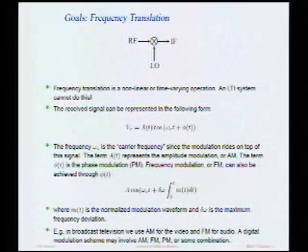Now, why do we need to perform frequency translation? Well, that's because most of the time we can't just transmit the raw baseband data. The baseband data is the information source that we talked about earlier. So for instance, my voice, if I were to capture that electronically in an analog fashion, has a bandwidth of, let's say, 5 kilohertz. If you have a really high voice, maybe it's 7 kilohertz. If you're trying to transmit music with really high fidelity, maybe it's 20 kilohertz.